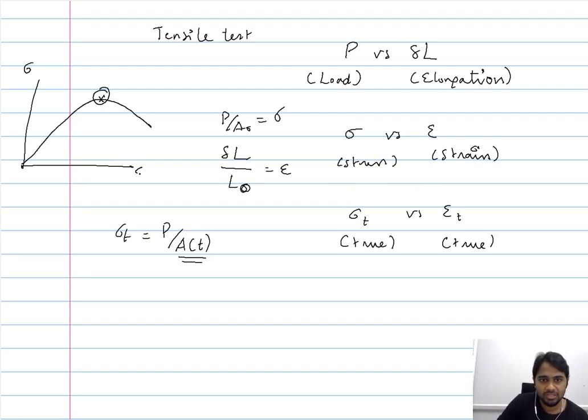Before this point we had an understanding that with increase in the strain you need to increase the stress. However, beyond this point there appears to be a drastic change, and we saw that this change was primarily due to the necking or geometrical change in the sample, and we were able to account for this change in the behavior or this rather ambiguous point.